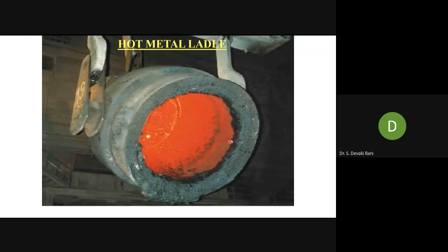So here, this ladle is also a steel shell lined inside with refractory bricks. It is a container to take the hot metal. It is a container to charge the hot metal into the steel plant. It is a container where metallurgical operations can be done. That is a function of a ladle. A ladle is simply a storage vessel, or a storage vessel plus some metallurgical operations can be done. A ladle is a transporting vessel for the hot metal from the blast furnace to the steel plant.